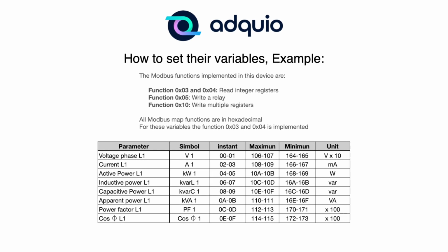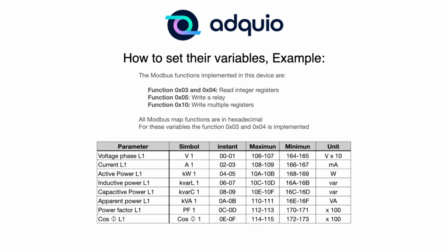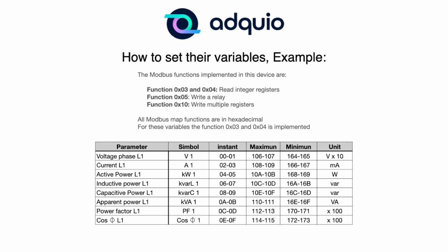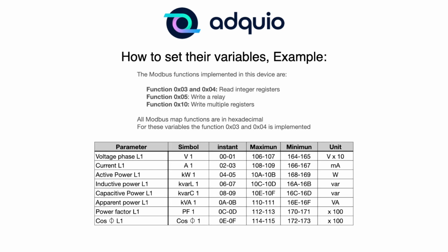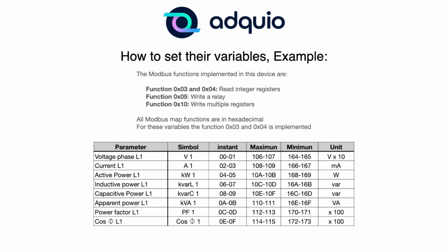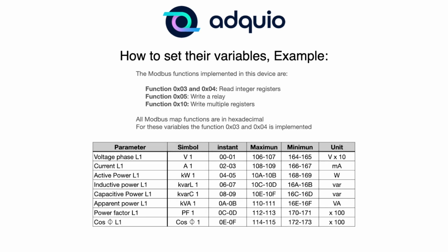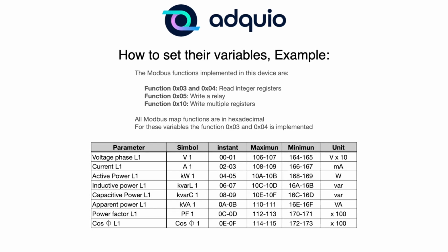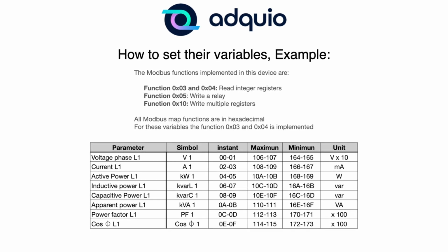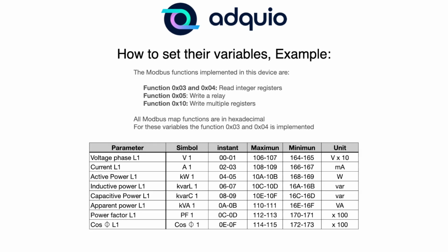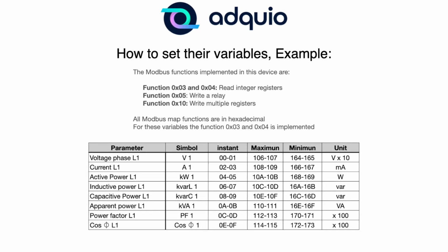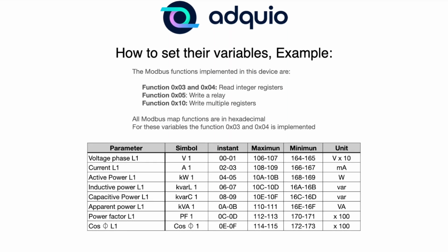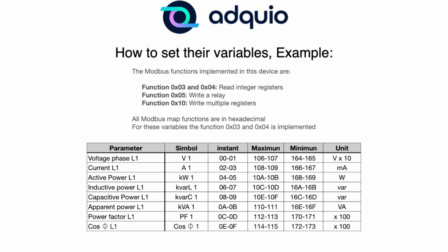If nothing else is specified, we can extract the size of the variable from that information, that O1 comes to us. In that case, as it indicates that it occupies from position 0 to 1, we know that it will occupy 2 blocks of 16 bits, therefore, we know that an integer value is being stored there, a 32-bit integer value. Obviously, we are also very interested in the last column, where it usually tells you if that variable is multiplied by 10, by 1000, etc., although it is not entirely accurate, as we have just seen.